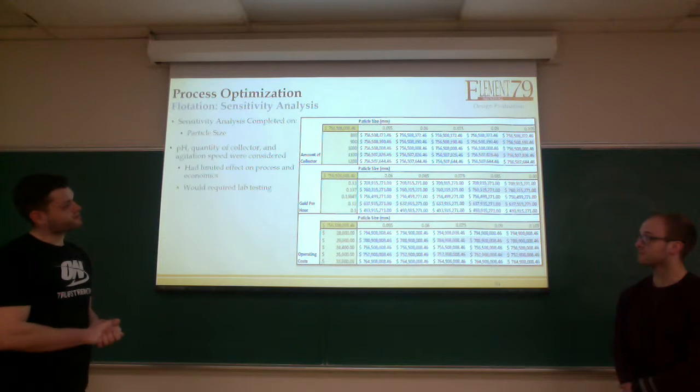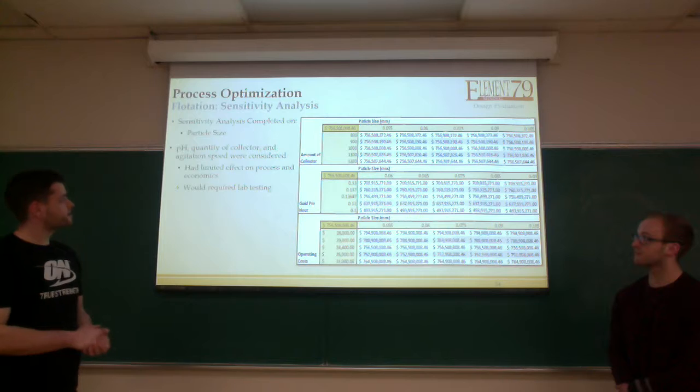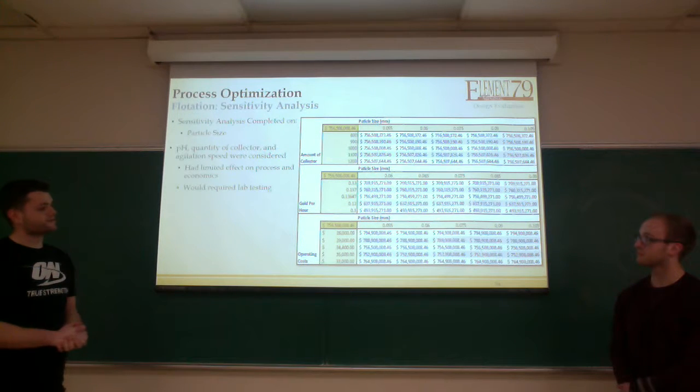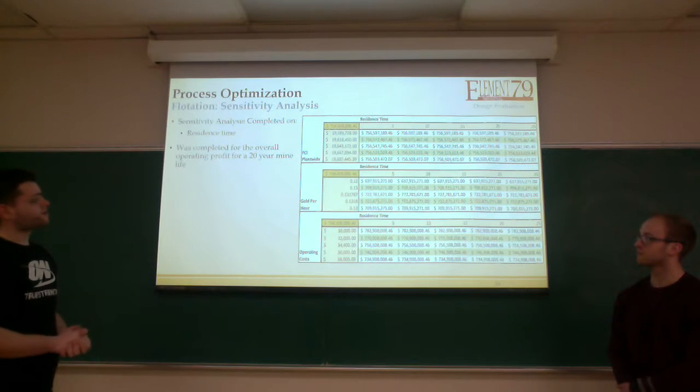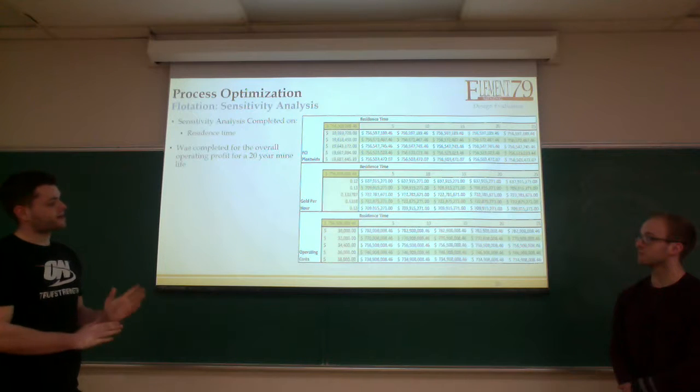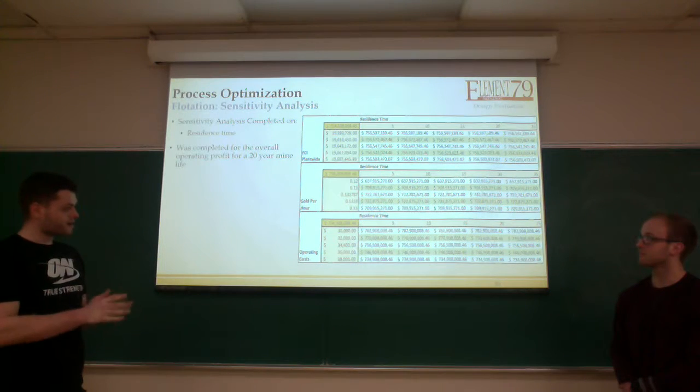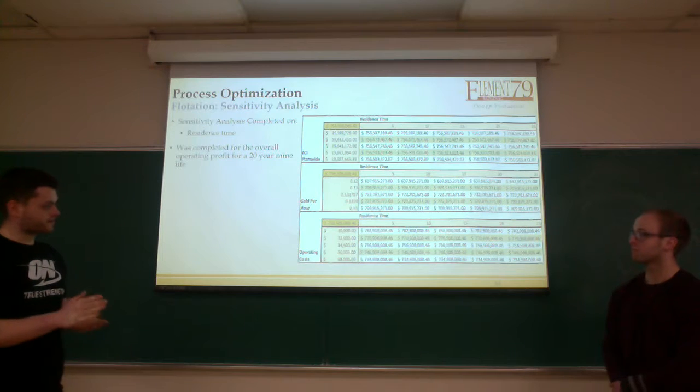So as you can see, there isn't much variation due to particle size. And if we look on the next slide, we can see that residence time also doesn't have a huge impact, and the most profitable is where our residence time is now, which is around 15 minutes.